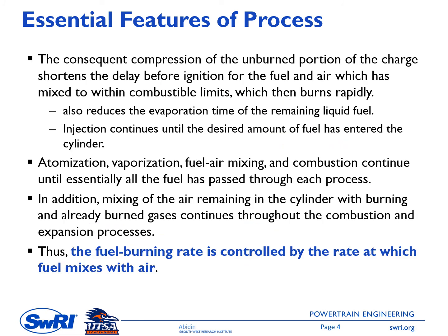The consequent compression of the unburned portion of the charge shortens the delay before the ignition for the fuel and air. So this makes sense because of the high pressure and high temperature.